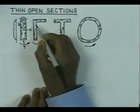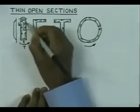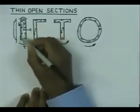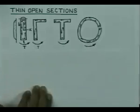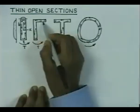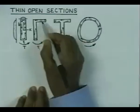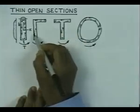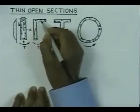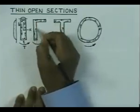Neglecting this junction, the shape of the membrane over this portion we can consider to be the same as the shape of the membrane here. Similarly, the shape of the membrane over this segment can be compared with the shape of the membrane here. And since the stress is going to remain constant at the edges, we can write the stresses in terms of the angle of twist per unit length and the thickness here. For this segment also we can write the stresses in terms of the angle of twist per unit length and the thickness here. And the torque capacity for this portion can be written in terms of the angle of twist per unit length, the length of this segment and the thickness. For this portion also we can write in a similar fashion.